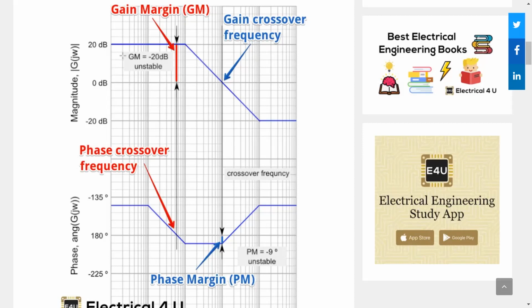So let's say the controller shifts us by -10 decibels. It'll probably be something like this. If it only shifted the decibels, that is what we will see, this new graph. Sounds good. We still are stable.